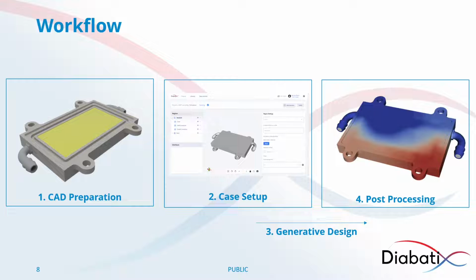Once the CAD file is prepared, you can make the case setup. That's something that you need to do in the Diabatix platform, so in your browser. Once that is done, we can start the generative design. From there on, you can relax, you can do other things, and you need to wait for the result to be ready. That means that on the supercomputer, your design is calculating. Once that is done, you get a notification and you can start the post-processing of your case. You can have a look at the results, you can generate some images for internal use, or you can download the step files, for instance.